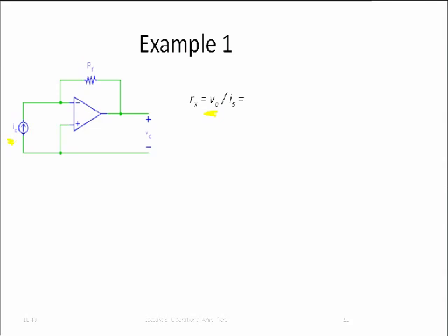So now we want to analyze the circuit in order to figure out the value of this Rx. What's the first thing we're going to do? You're jumping a little bit ahead, but you're almost right. But really what we're going to do, in a blink of a second, is say there is a feedback loop. It's negative feedback because we go back to this minus terminal here. That's really the thing that we have to verify. You have to do that.